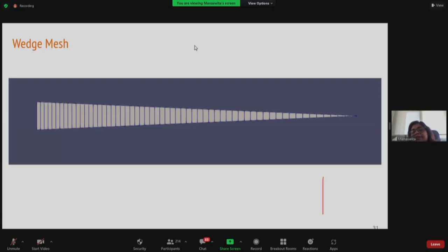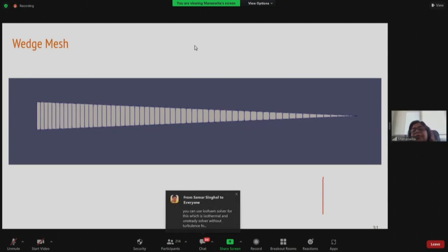Yeah. No, for example, let's take an example of a flapping wing. If you are simulating such kind of a flow, you'll have a zero pressure gradient even at the outlet. Sometimes they use that, or sometimes they even use a convection boundary condition. Sorry, ma'am, it's problem dependent. I'll have a look at the problem. If I look at the problem, I'll be able to tell you. So boundary conditions are essentially problem dependent.